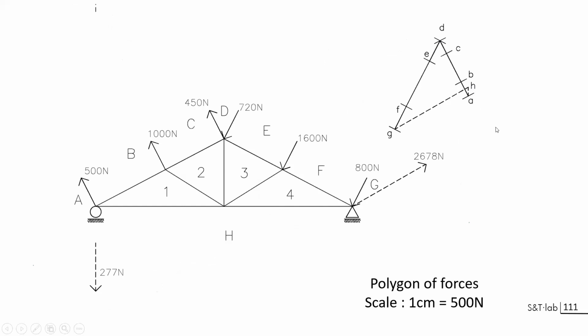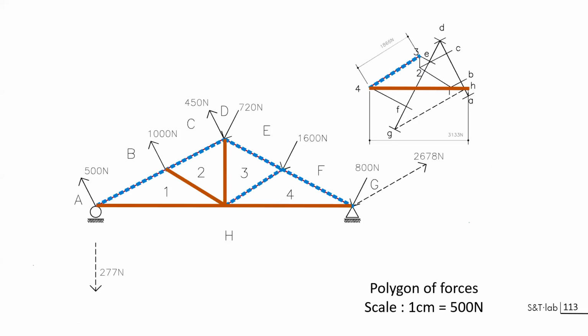We can move again with adding the other bars and with parallels to each of these bars. For instance, if you have C2 here, you know C, and you have 2 appearing here as an intersection with the vertical passing to 3. And this is an incremental construction that you are able to do. Of course, the same applies in deciding the several forces and their directions, and the magnitude of the forces. You could say, well, I could guess that this bar will be in traction here, and that one will remain in compression. So again, solving the system.